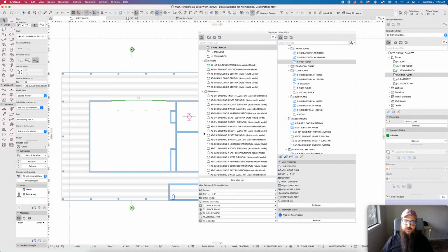Once the viewpoints are set up, as an example of this section marker that I have right here, I can then create views. Those views are sort of the view map, the staging point where we get ready to put these viewpoints onto a layout. The layout is sort of the final sheet that these go out to PDF or to print on.